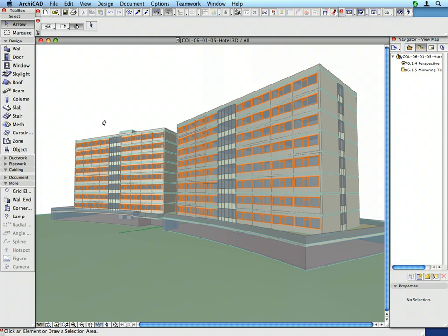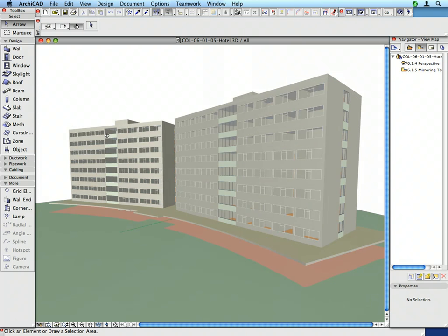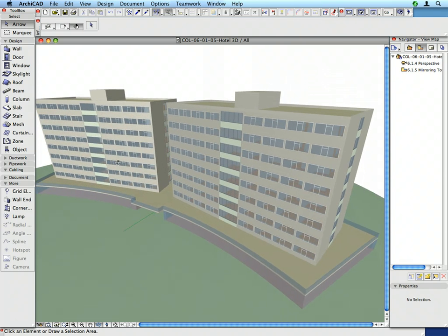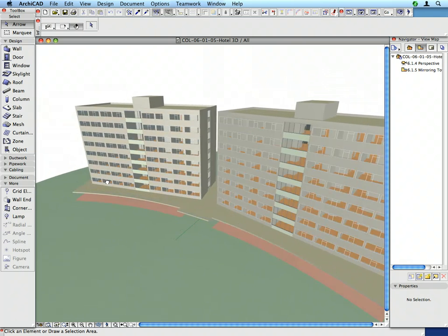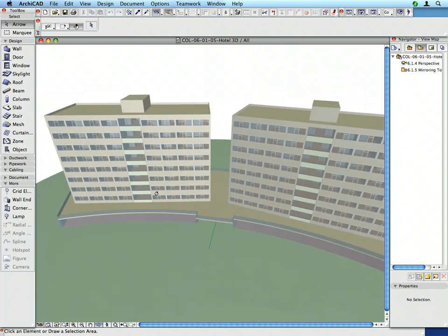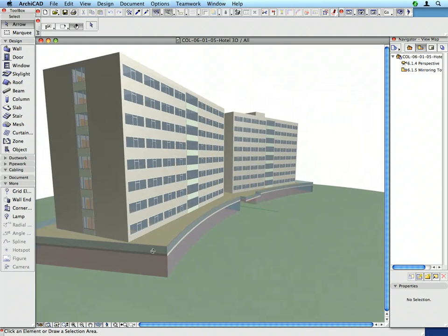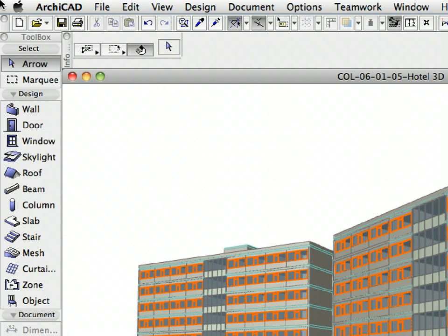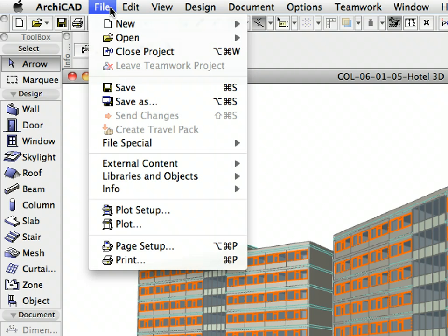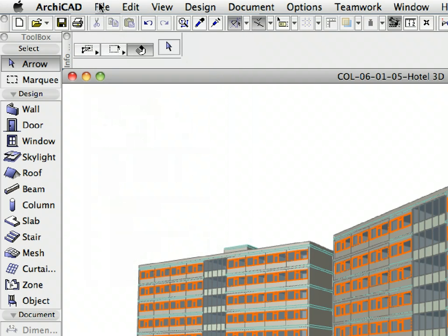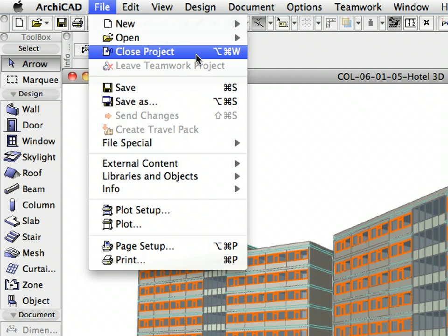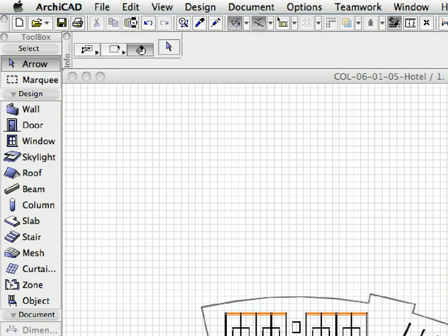In this training step, you got a picture about the basic concept of the ArchiCAD Hotlinked Module system. As you experienced, a lot of time can be saved with hotlinks when dealing with large projects containing repetitive elements. Save and close the project file using the File, Save, and File, Close menu commands, and proceed to the next movie on the ArchiCAD Movie Player.